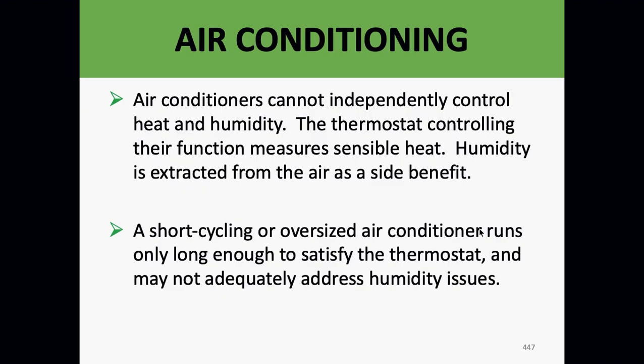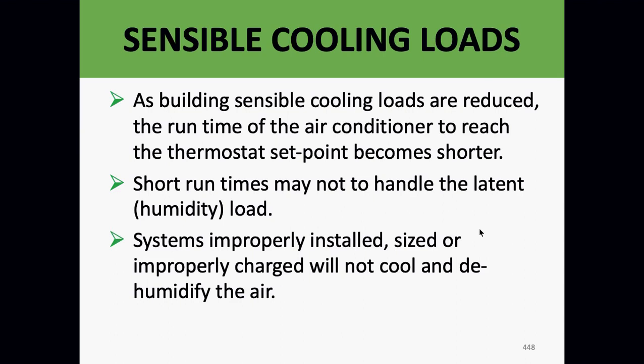Air conditioners cannot independently control heat and humidity. The thermostat, what we were talking about earlier, controlling the function, measures sensible heat. Humidity is extracted from the air as a side benefit of the cooling process, but I cannot control an air conditioner based on humidity. A short-cycling or oversized air conditioner runs only long enough to satisfy the thermostat. It doesn't adequately address humidity issues. So sometimes you have to put in a dehumidifier if this situation is happening.